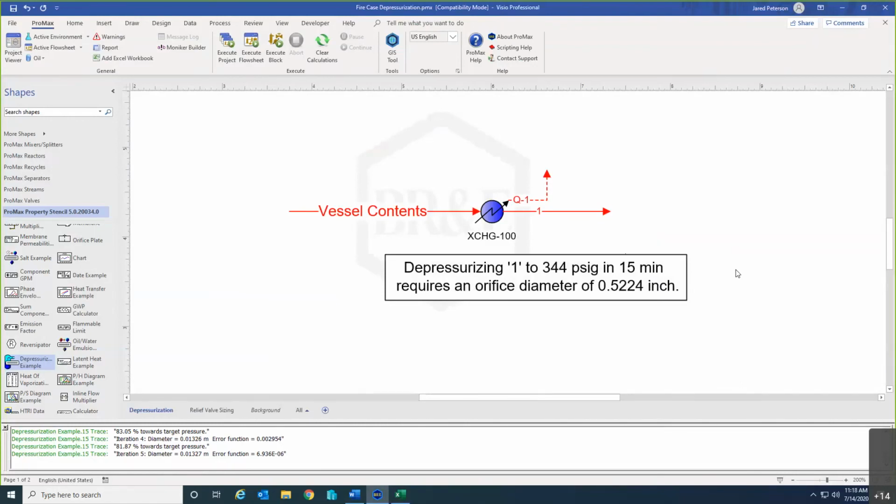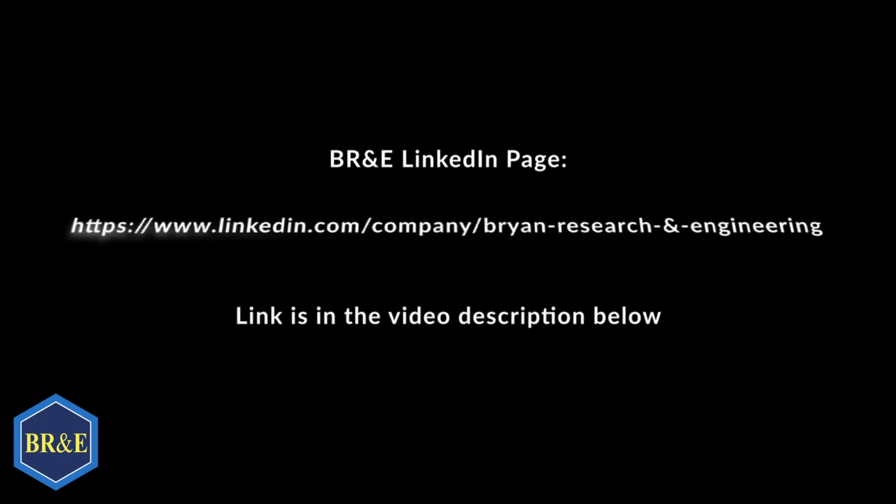Are there any questions? It looks like Wolfu has a question here. With 0, you assume the fire heat input is constant. We do end up assuming it is constant. Variable heat input along with liquid level drop. To the best of my knowledge, we do not calculate that. I would have to look into the code to see if that changes. I believe we keep it at whatever value your unwetted area factor is and keep it constant. That's a good question. I can look into that, but I believe it is constant, yes.